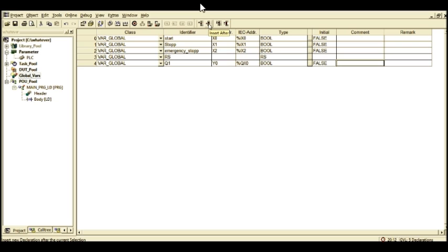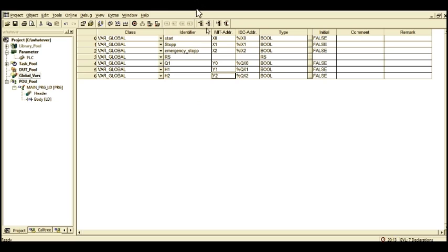We also have to use some indicator lights, which will be H1, H2 and H3. H1 is for indicating when the engine is going to start. That will be green. H2 will be the current light, which tells us if there is current on the PLC. And the H3 is for stop.